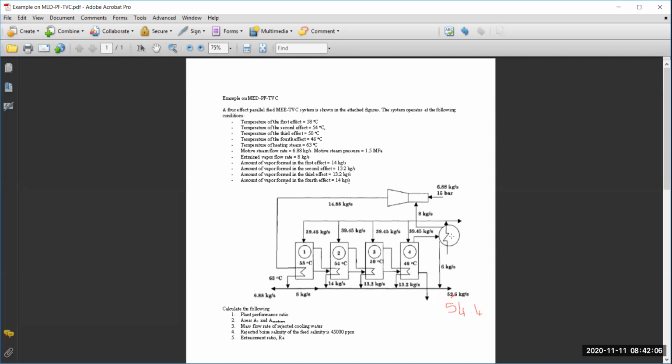Sorry, it's not the area, actually, I'm talking about the flow rate. So it should be M dot feed plus M dot cooling water, times Cp, times the temperature difference, which is Tf minus T cooling water. We are heating all this cooling water from T cooling water to Tf, using most of it and rejecting a part, so that we can calculate how much is being rejected.